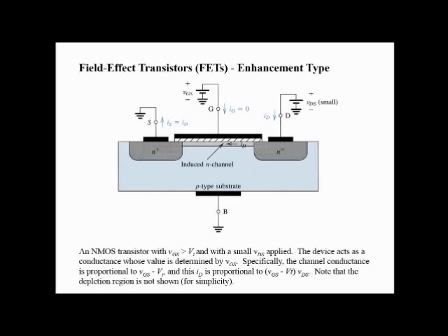If you apply forward bias, if you apply positive voltage across this gate terminal, then these n channel electrons in this part will be attracted and this channel opens up. So this is the basic reason why forward bias is given through the gate potential, and this positive potential enhances the n channel and makes the path easier for the flow of current.